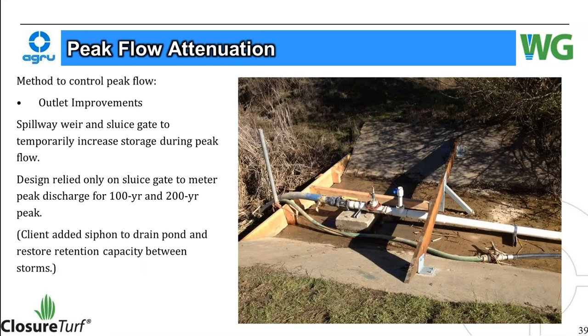The client added the siphon that you can see here to drain the pond and restore retention capacity between storms. So there are ways to cope with the higher runoff potential of ClosureTurf. You just got to pull out your engineering cap and come up with the solutions.